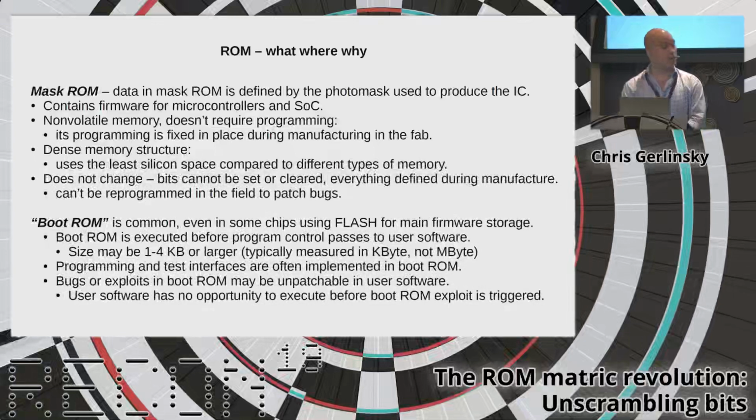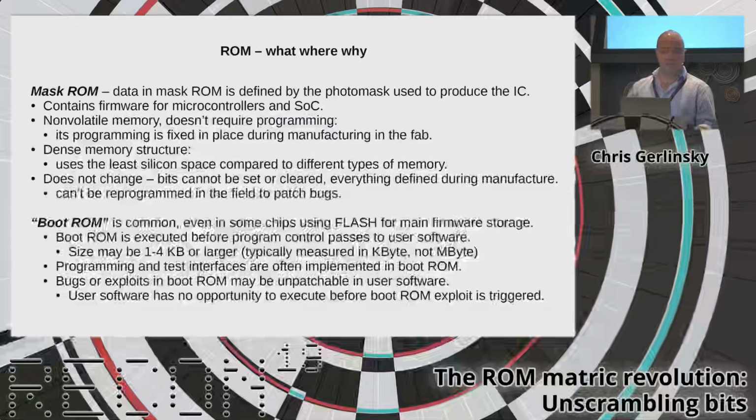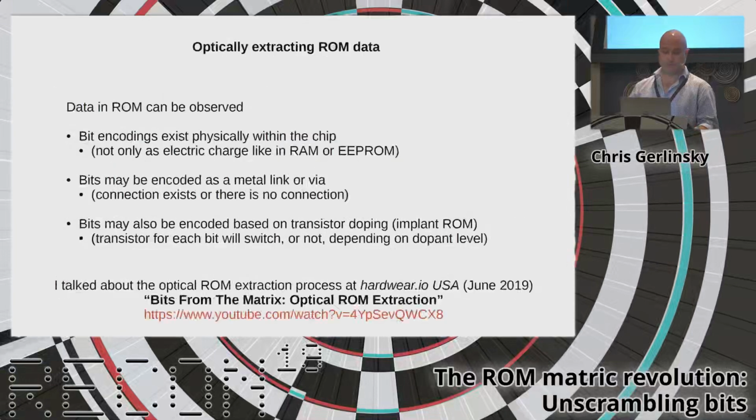A boot ROM is a common use of it. That's a ROM that will execute as soon as you reset a chip, before it even runs any of the user code inside of the chip. These boot ROMs are usually quite small, like a few kilobytes, and they're interesting to look at because as an attacker, if you can exploit the boot ROM, then you have a way to exploit that platform without even worrying about the actual user software that's inside of that chip.